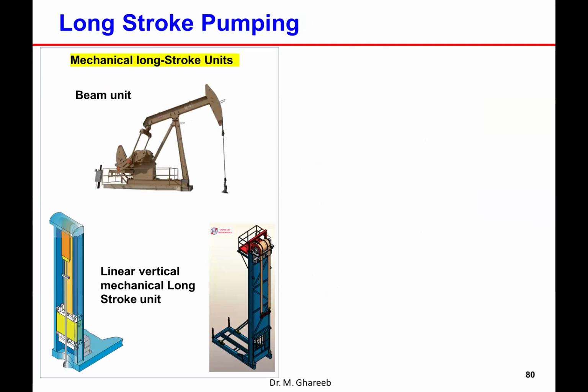And this allows not only running the well to produce high volume, because when I use a longer rod string, I can produce more volume. The volume the pump displaces is a function of what? Plunger size, pump size, and stroke length, how much the stroke goes up and down, plus the strokes per minute, and so on. With a longer stroke length, this allows you to produce more.